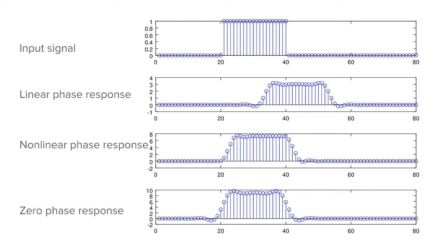It stays like that. Nonlinear phase response, I think it was a second degree system. Quite familiar from what you get from any analog system. So there's a little bit of overshoot, but then actually it comes as an undershoot for the falling edge. On linear phase response, you have an equal amount of undershoot and overshoot for both the rising and falling edge.